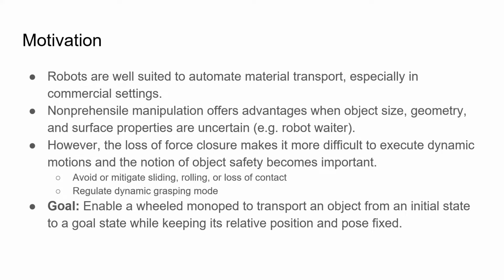We are interested in regulating the dynamic grasping mode during object transport, which means that the object effectively stays stuck to the end effector. We define this mode as the safe mode, where the object's relative position and pose are fixed relative to the end effector.